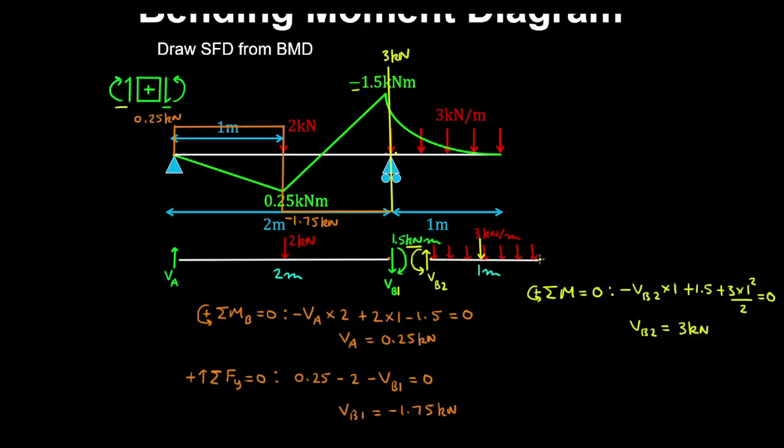And if you assume there's a shear force on the overhang, you can verify that by vertical equilibrium of forces, that shear force is 0. And the shear force diagram is linear on this portion of the beam because there's a uniformly distributed load. And you can also verify that this reaction here is 4.75 kilonewtons, which is equal to the jump in the shear force across the support.